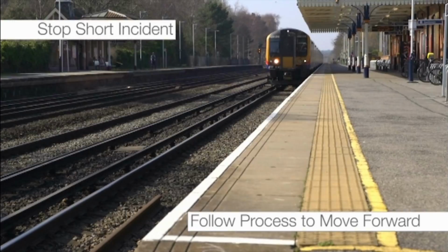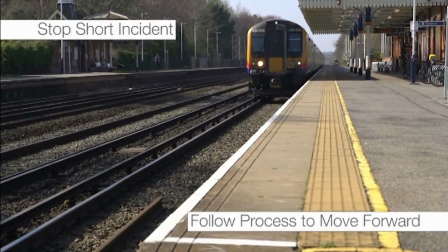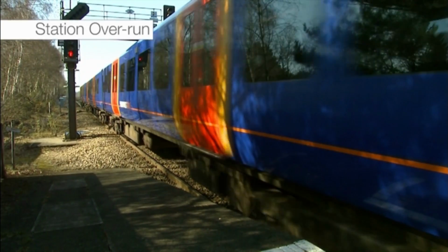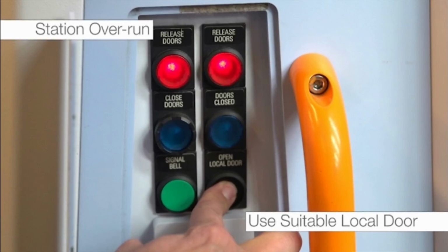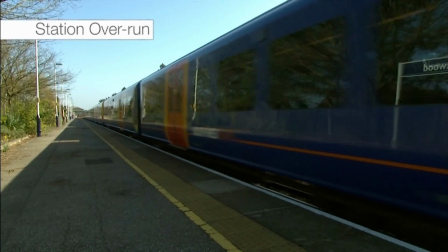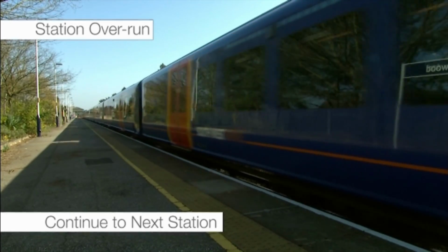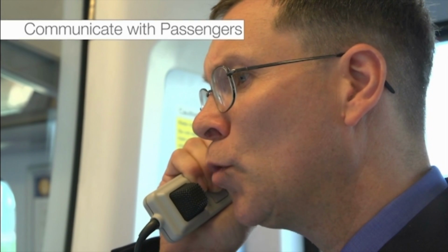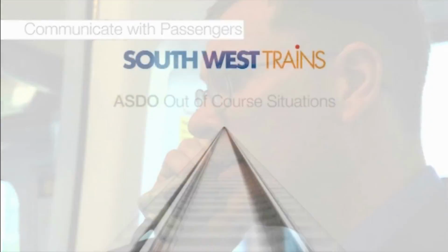Arrange for the train to be moved forward into the platform to allow correct door release to take place. For a station overrun on short platforms, passengers must use a suitable local door. If there are no suitable local doors on the platform, the train must continue to the next station. In either situation, it is important to keep passengers informed. Delay in opening the doors because the train is not correctly accommodated.